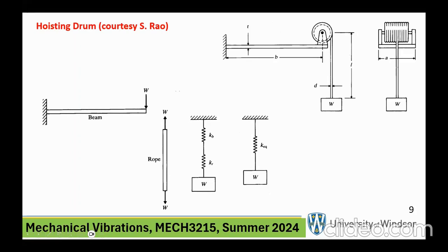It stretches, that's what a spring is. So if you know the cross section and you know the length and things like that, we did this last week also. And AE over L, if you think about the rod, a rope acts similar to a rod under extension, AE over L. We did these things last week. So these two springs both resist, but they are in series. Just think about it. This spring and that spring, they're not parallel, they're in series.